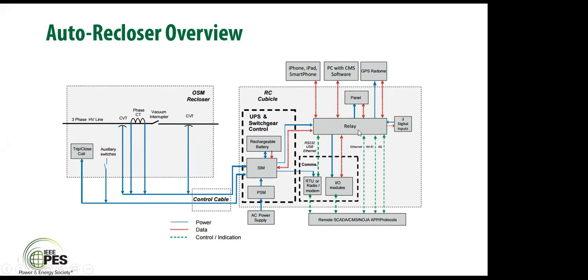Based on the set algorithm, the relay decides which protection scheme to activate. Overcurrent, arc fault, negative phase sequence, directional protection, all types of protection algorithms are set in the relay. Based on the received current and voltage data, the relay decides which protection algorithm to activate.